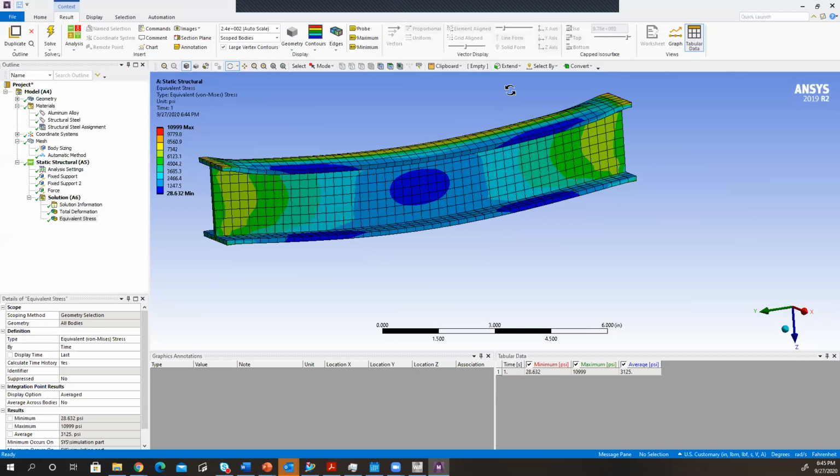I guess the way I would do it, I've never done it before, but based on my brief experience with ANSYS, in the 3D model I would probably model a base on the sphere. Let's say it's a bowling ball. I would model a base and some sort of 4-point constraints on it so that it theoretically doesn't move, and then I would apply the force on top.